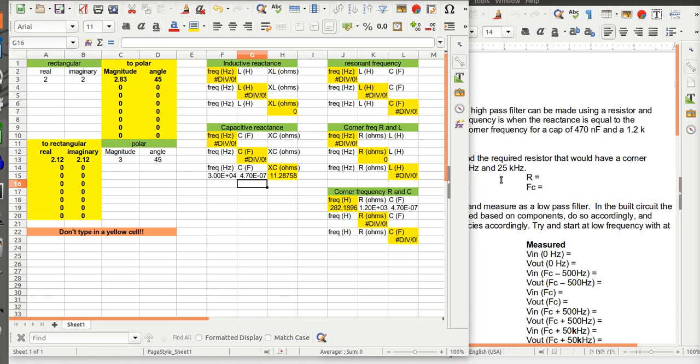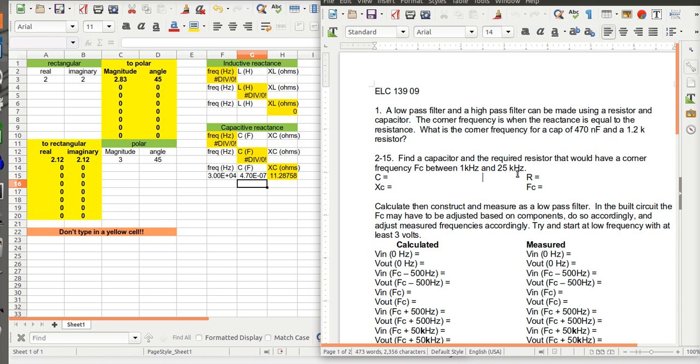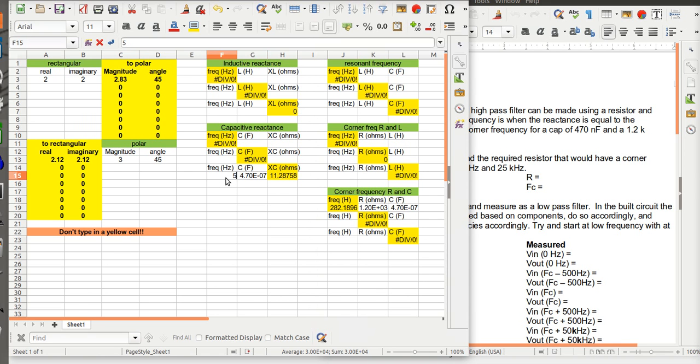Obviously, I want to go down a little bit, so you want to be closer to 1K hertz than 25K hertz for your corner frequency, because that will, I think, raise your resistance. Let's double check that. So let's go down to 500 hertz. That gets me to 677. So somewhere between 11 and 677 is where it's going to work out, and that puts you outside the range.